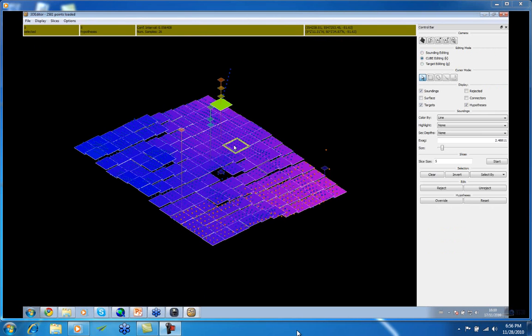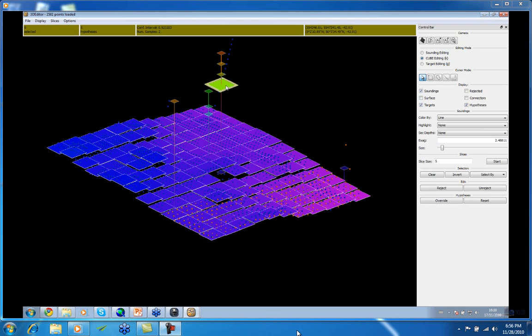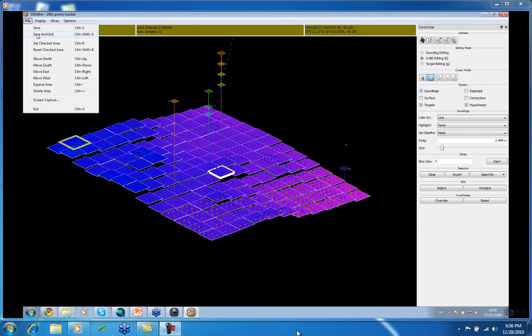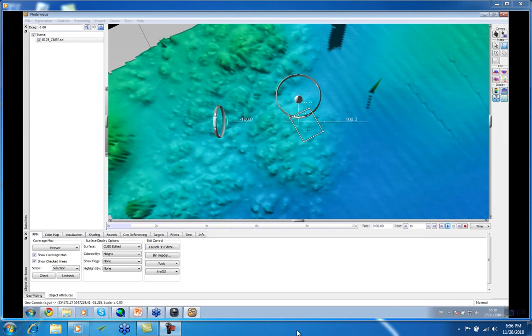Where the cube thinks it might be, but it says it's not the right one, you've got a little square. Now, because you've got the right answer, you can just come over to this square, select the square, and then just do override, and that will override what the cube solution says, and save as an edit, and lo and behold, your cube surface is updated. Now, that's what you do if the cube has got the right solution.